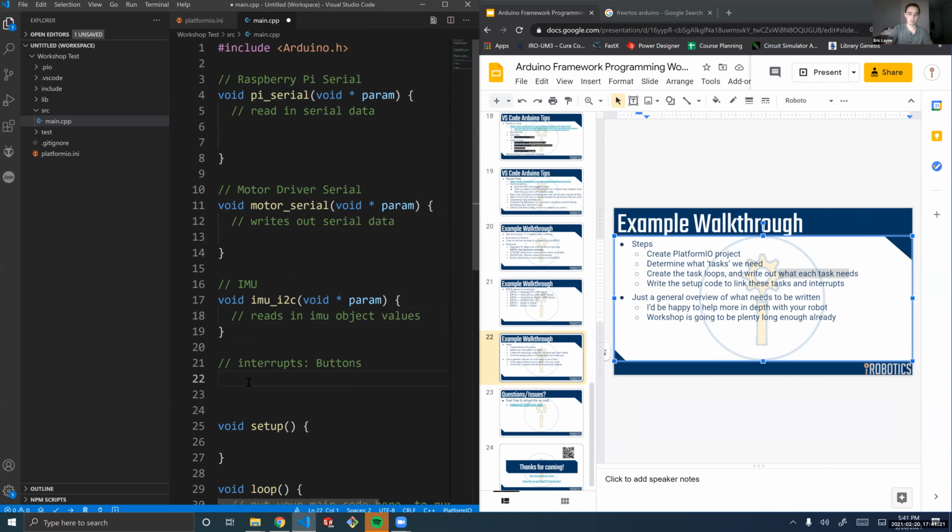And then we want two functions for the interrupts. So the format is given on the Arduino reference page, but basically it's just going to be like button 0 int, that's just what I'm going to name it. It takes no arguments, so it's just open close parenthesis, curly braces to say this is a function.